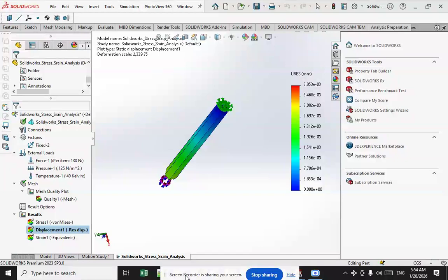When the applied loads cause permanent deformation, one must use more complicated constitutive equations that can account for the physical processes involved: plastic flow, fracture, phase change, and so on. Engineered structures are usually designed so that the maximum expected stresses are well within the realm of linear elasticity.